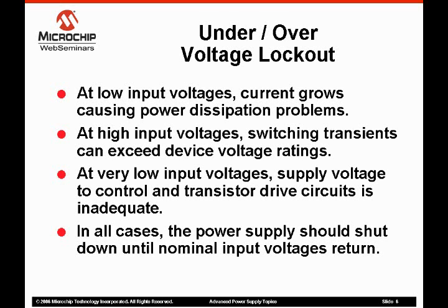Excessively low input voltages can cause faulty operation of the control circuitry and insufficient gate drive voltage to the MOSFETs and the IGBTs. High input voltages can damage transistors and other components as their voltage ratings are exceeded. Be wary of switching generated transients, which in a high input voltage condition may exceed the transistor specifications.